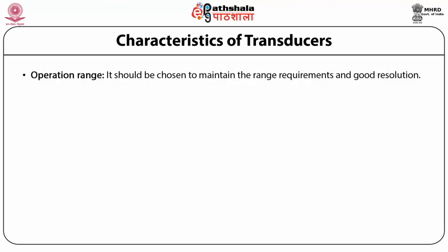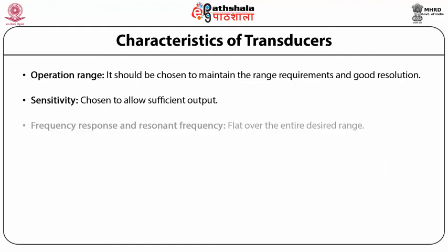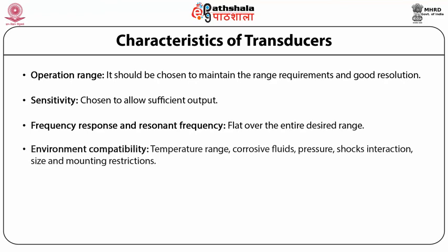It should be chosen to maintain the range requirements and good resolution. Next is the sensitivity, which is chosen to allow the sufficient output. Frequency response and resonant frequency, the flat over the entire desired range. Next is environment compatibility, that is temperature range, corrosive fluids, pressure, shocks interaction, size and mounting restrictions.